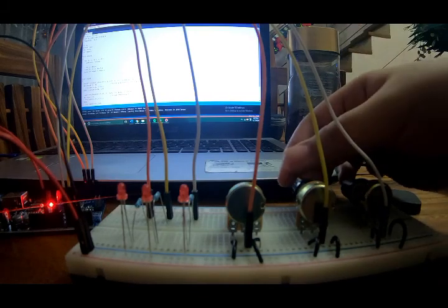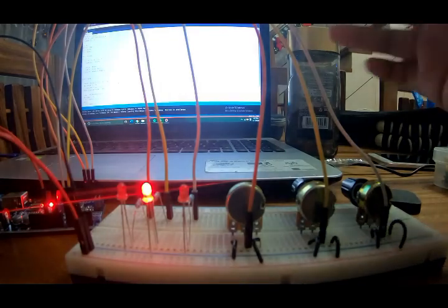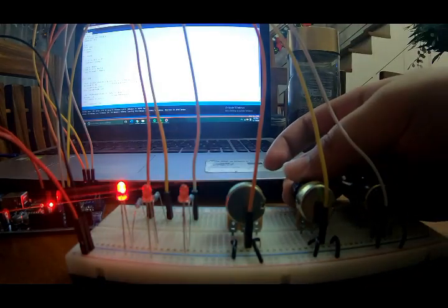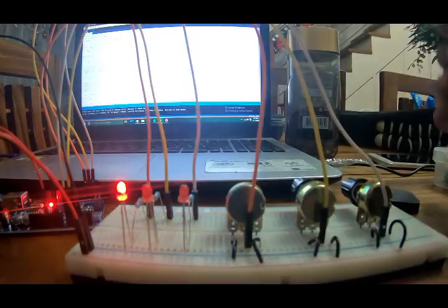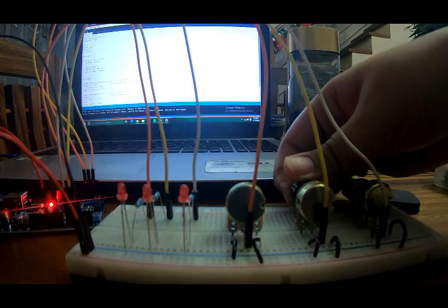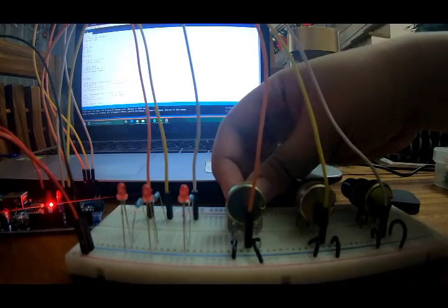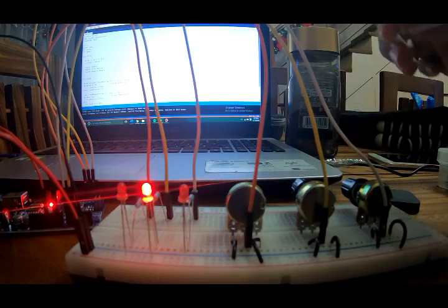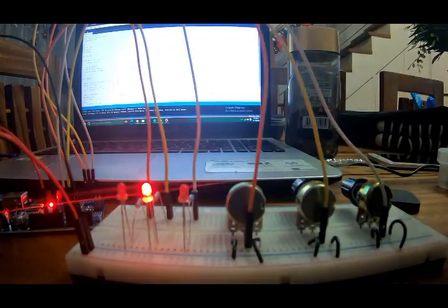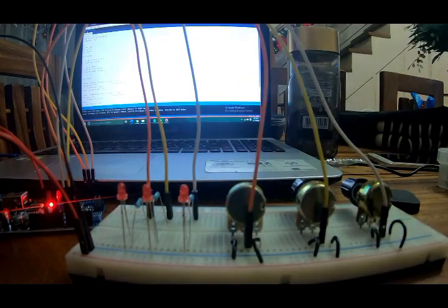Meanwhile, for the temperature, if it is too high, pin 3 will turn on the water bubbler. Or if it is too low, pin 4 will turn on the aquarium lights. Let's put them back to normal. And lastly, for the dissolved oxygen, if the amount of oxygen is too low, then pin 3 will turn on. But if it's just right, it will turn off.